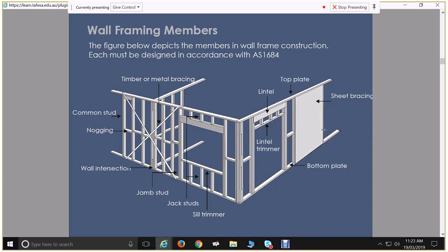But if you provide that sheet bracing all the way around, you get an incredibly rigid frame, so it ties everything together really well. But you also get compartmentalisation of that frame in terms of airflow. So when it comes to insulating your house, yes, you put insulation in between your studs, but then if you've got a sheet covering all the way around, that helps lock that in. It creates these air pockets and it provides you with additional insulation. So for a few $100, you can get a really rigid frame and a wall frame which is all fully sealed.